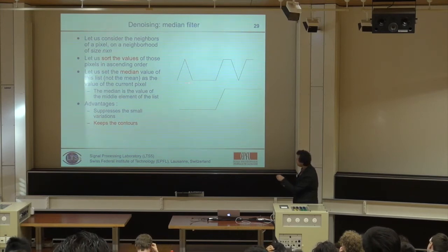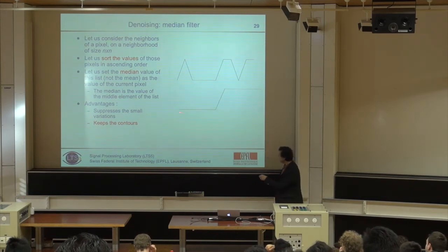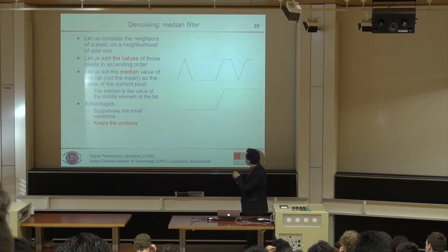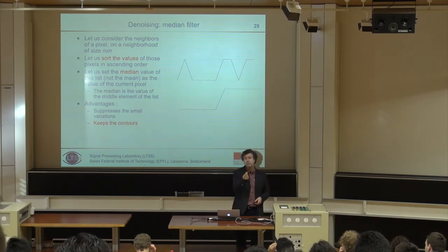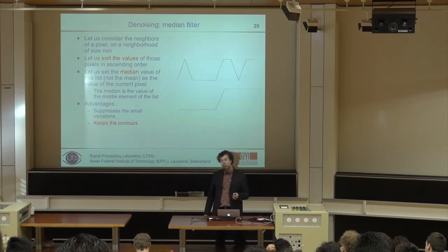This is really an exception because its neighbors are 0. But the rest is clearly zeros becoming 1. And after the median filtering, you really get that. So it removes what is really an exception in the middle. But when you have a steady transition from one region to the other, it is kept. And that is the beauty of the median filter.